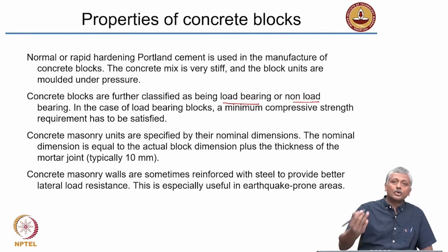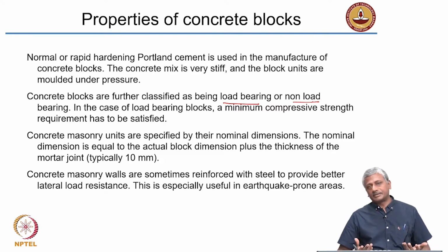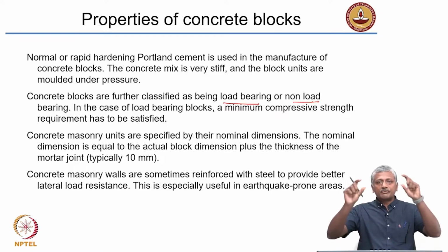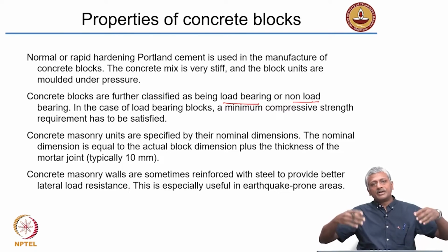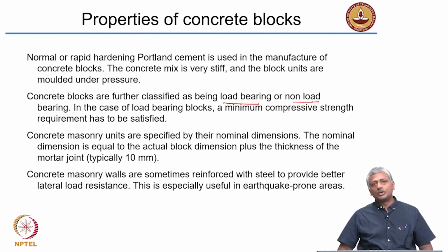Now, in case of non-load bearing masonry, where do you find that? In most of our modern structures, you have frames of reinforced concrete and the walls are basically filled in afterwards. The filled in walls do not really take up the load of the structure. They have to only support their own self weight. Those are called non-load bearing walls. In such cases, you can use lightweight concrete blocks. They speed up construction like anything and also improve the insulating properties of the wall.